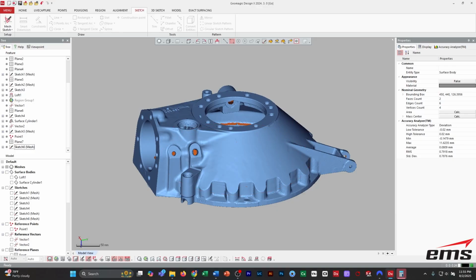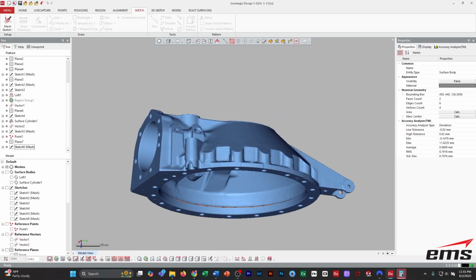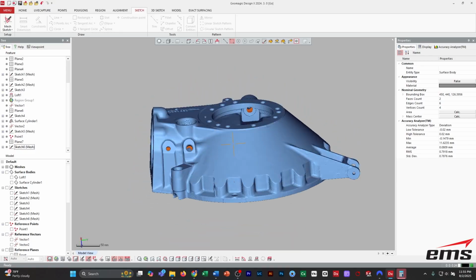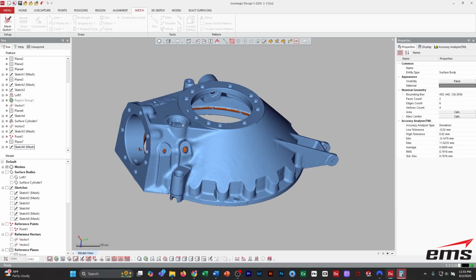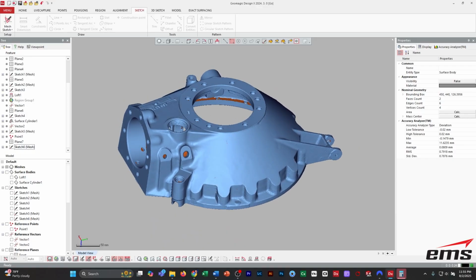Well, with a 3D scanner, you just scan the part because we will establish all that here in the software. So we're not locked down. We can freely move the part around. So it's much easier because you do all the measuring later. You establish your coordinates later. So this part we can scan in a couple of minutes and it's done. And then you can go offline and do all these measurements you want to do. So next, what I'll do is we'll whip up a real quick report and I'll just show what that looks like.